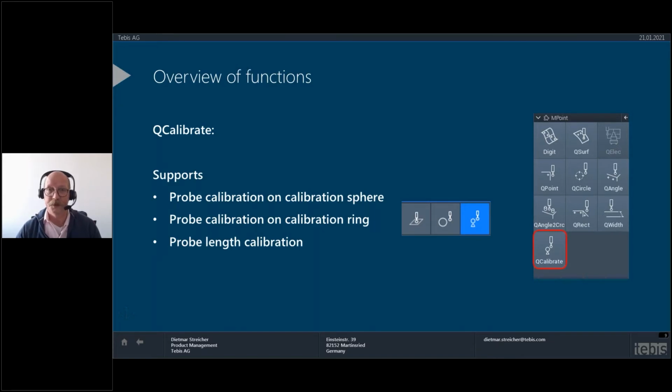So it makes sense to make a little NC program to do a first calibration, then do a setup compensation on the sphere. You will measure with your first calibration data, with your beta calibration data, the center of the sphere again, and you put the origin exactly at the center of the sphere. And now you do a recalibration, sorry. And so now you will get better calibration data because the offset has been placed better, and you're doing one more loop for an increase in accuracy. So that's the idea behind a calibration function within a CAM program.